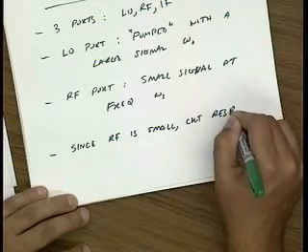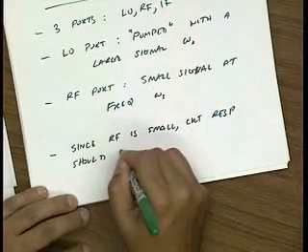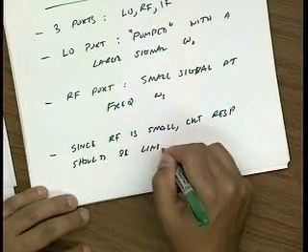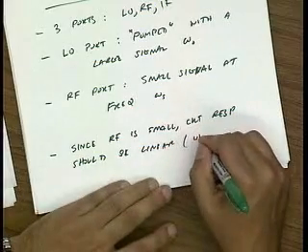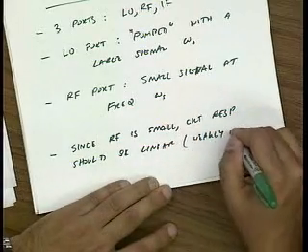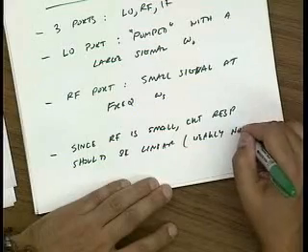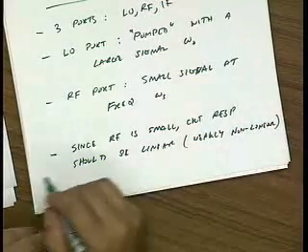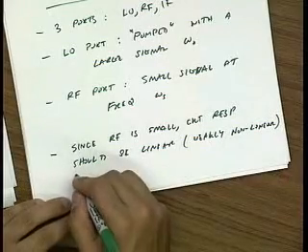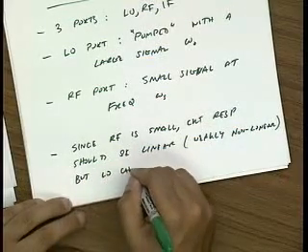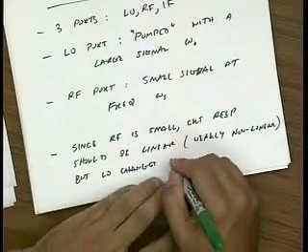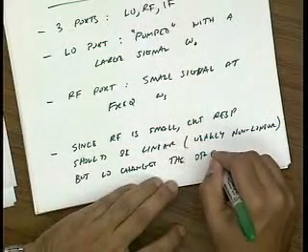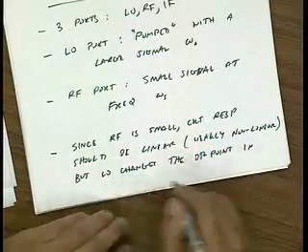The circuit response should be linear, or at best weakly nonlinear. So the Taylor series stuff we did should be valid. But the LO changes the operating point in a periodic fashion.